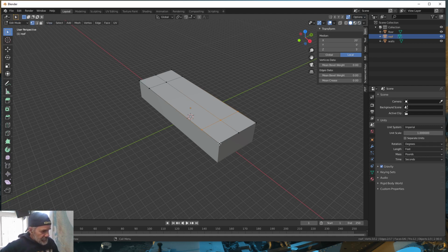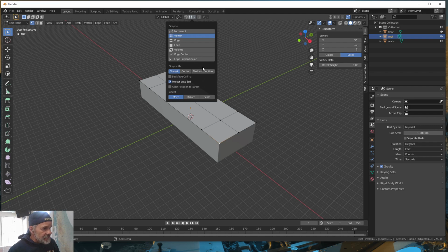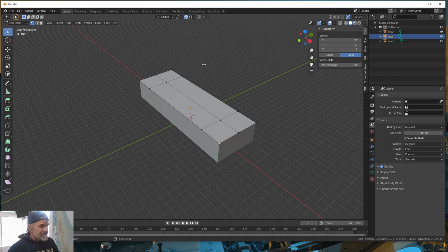Then, select a vertex and hit E. Oh, make sure that your vertex selection is on, active, and snap is on. All right, so I have this vertice selected. Hit E and snap to this one. It will automatically split this polygon. So if I go to Polygon Select, now it automatically splits those 2 polygons, right? Okay, so let's go back into Vertices Select and select this vertice, hit E to extrude, snap it there. Come down here, select that, E, snap. Select that one, E, snap. Okay, so now I have all of these